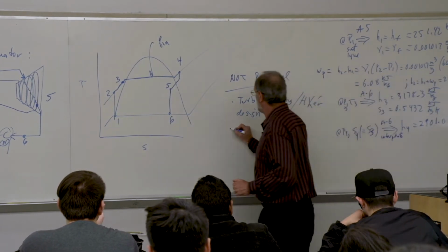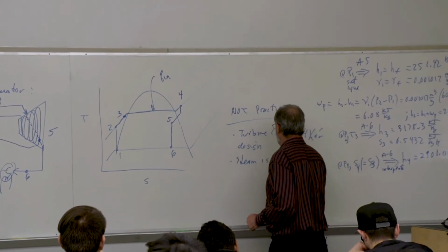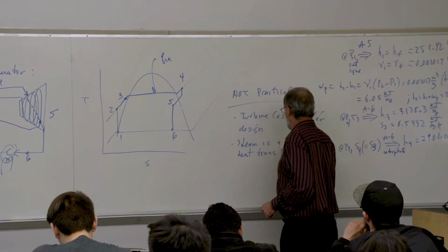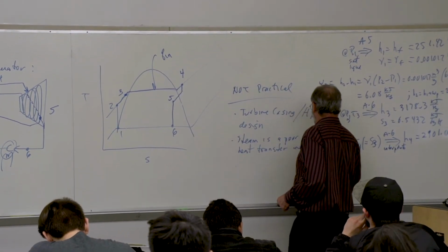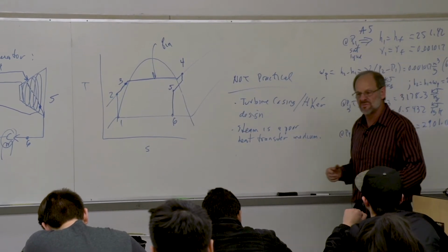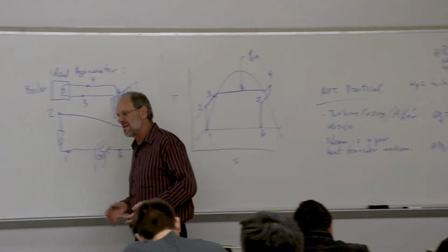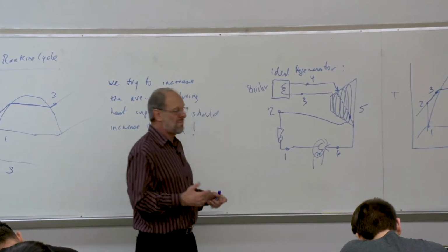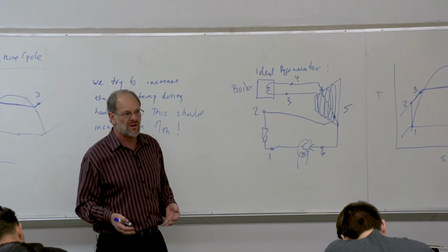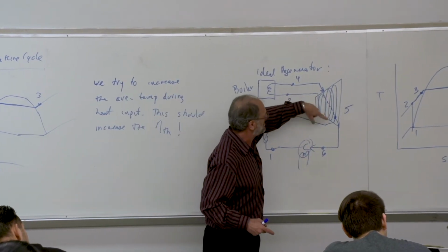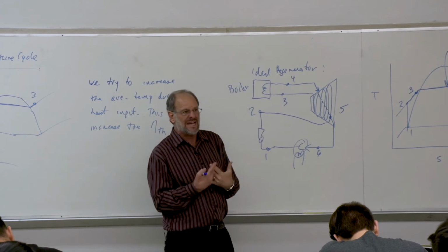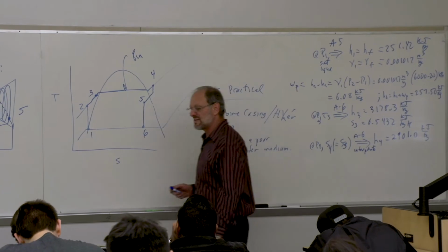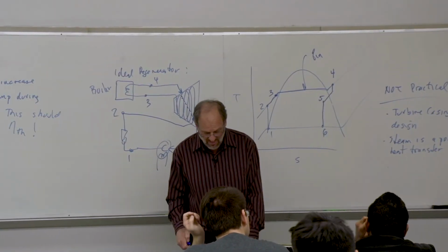Another thing that should be noted is that steam is a very poor heat transfer medium. And we're definitely, in this particular case, exchanging heat from steam. Now keep in mind that steam is a gas, right? And gases have a very low density. So to get any appreciable amount of heat transfer from a low density fluid, you need to have very large surface areas. So not only is it going to be hard designing it, but the physical area required to transfer heat from that steam may not even be sufficient. So the fact that steam is a poor heat transfer medium becomes another problem.